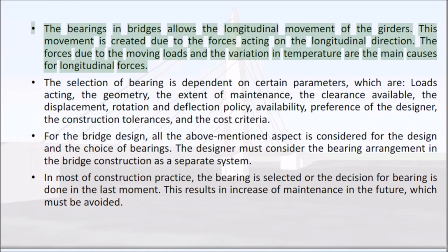The bearings in bridges allow the longitudinal movement of the girders. This movement is created due to the forces acting in the longitudinal direction. The forces due to the moving loads and the variation in temperature are the main causes for longitudinal forces.